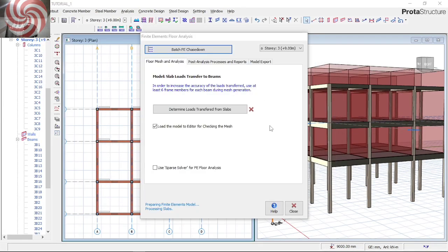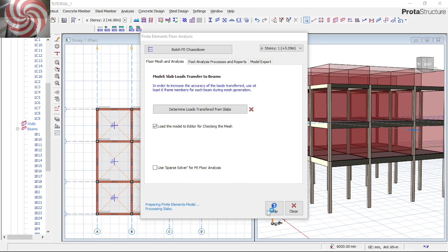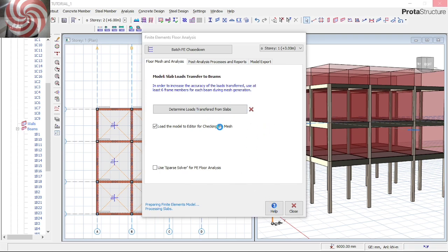It's going to chase down. Remember, in chasing down your building, you must stand at the last floor and bring it down till it finishes. You don't just stand at story 1, even though with this software, if you are mistakenly at story 1, it's going to take you to the last story. Then from there it will chase down all the loads evenly.